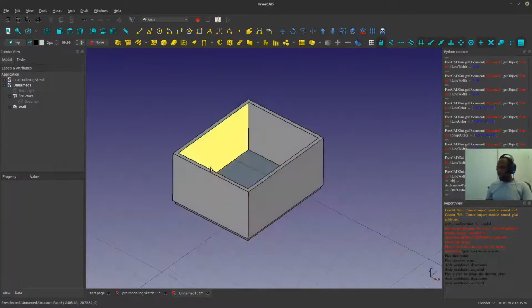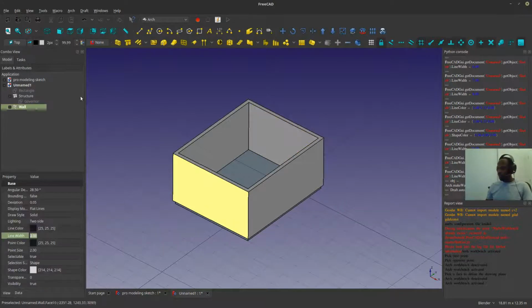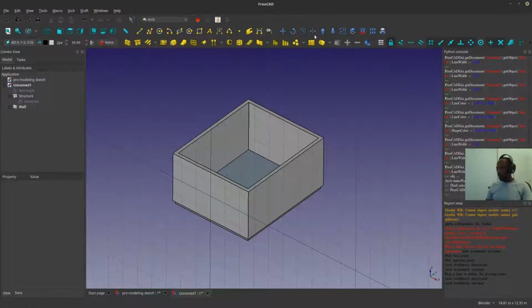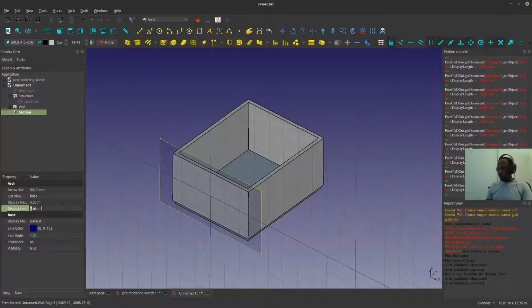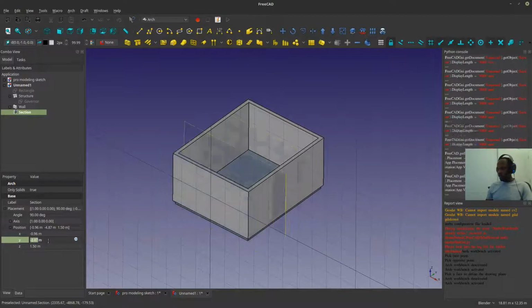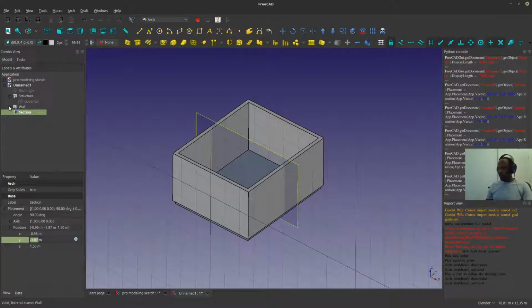First of all, let me add a section plane so we can see through what we're doing as well. So I'm gonna select this face, make sure my plane is there so that when I insert my section I can see that. Let's increase it about the size of the structure itself. That's good enough. And so what I want to do is move it a little bit into the center of it. That's the Y direction, so I'm going to scroll that, and that's good enough. Okay.